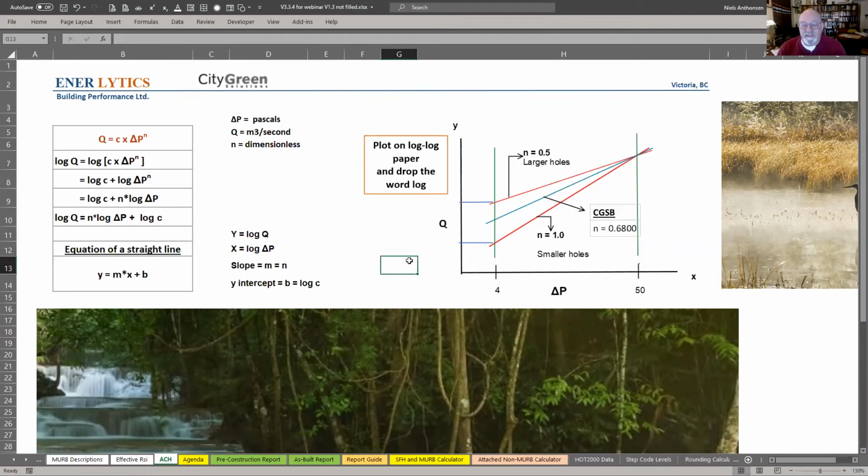We are certainly testing houses where they are testing down like 0.4, 0.5, even somebody 0.23, but I'm not quite confident in the accuracy of our manometers and that sort of thing down at those levels. I mean, they're spray foaming, they're using Aerobarrier, the spray powder that they're spraying in, doing all sorts of stuff right now to get really airtight.